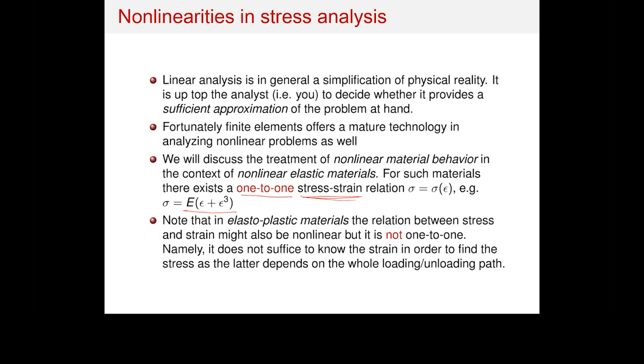And then the loads you have in there would stay the same. The self-weight is not going away. The dead loads you have in your structure are not going to go away. But what you have in there is just a change in the material properties due to the heat. And this will lead into, again, a nonlinear behavior. You face a serious nonlinearity in this case.